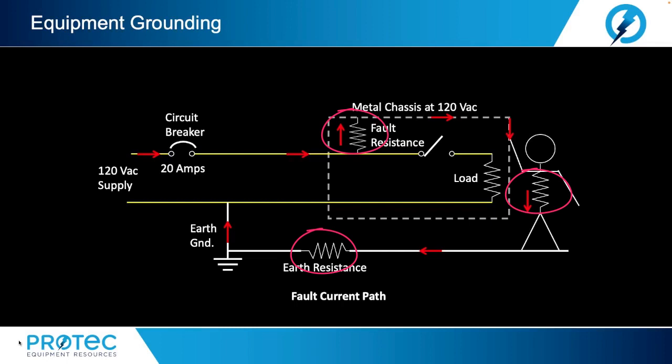The only requirement in the National Electrical Code, NEC, is that the resistance of the grounding electrode or ground rod be less than 25 ohms. Hence, even if the device is not isolated from ground or earth, the ground resistance may limit the fault current to below the trip point of the circuit breaker. Furthermore, there is usually considerable resistance between devices and earth ground. For example, the device may be sitting on a concrete slab.